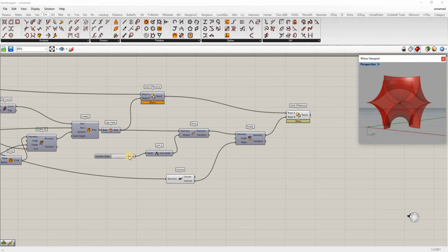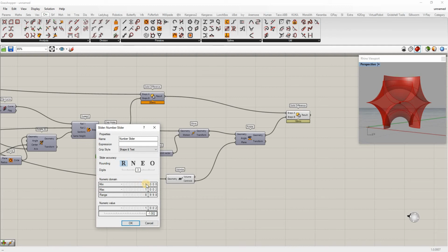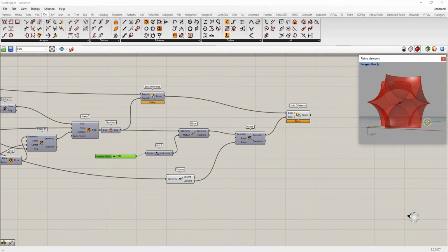1.002 because when I tried this before with just the -1, let's just make this a 1. And I made it just a -1, it didn't seem to cut that out. My guess is that these geometries are overlapping on an edge somewhere and it's causing some confusion.